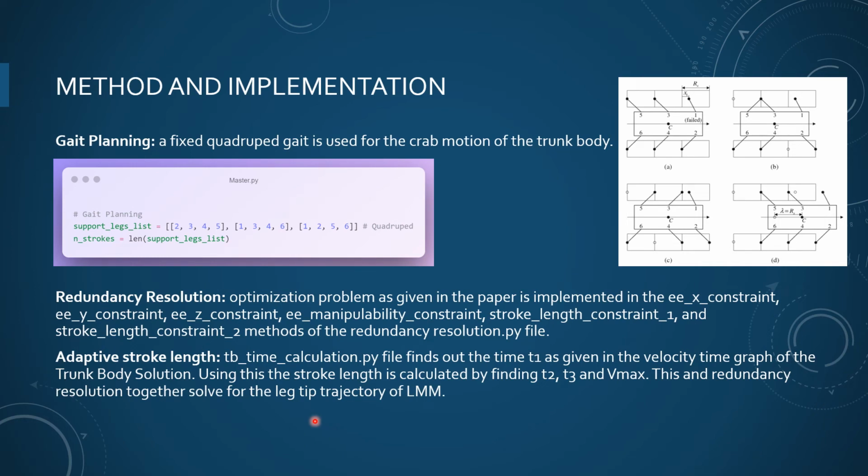Using this, the stroke length is calculated by finding T2, T3 and Vmax. All of these equations are used directly from the paper, and this coupled with the redundancy resolution together solve for the leg tip trajectory of the LMM.